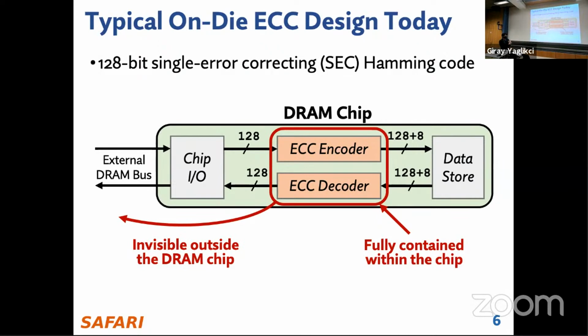And so they have the same problem, right? Now on-die ECC is interfering with their own testing. And so they very likely have their own bypass paths to just directly read from the data store, skip all of this or disable it or something, and then test whether the chip works. We've actually seen evidence that such a bypass path exists in some other non-DRAM devices, like other memory chips.